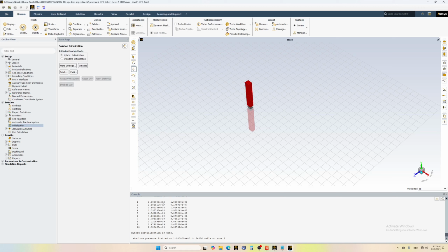And normally this value should be greater than 10 to minus 6. If it's not, then you will have a warning here. You don't have to worry about that one. The simulation might be okay. I mean, it might run properly. By any means, it doesn't mean that if you have here 10 to minus 9 or 10 to minus 12, the simulation will run without any problems.